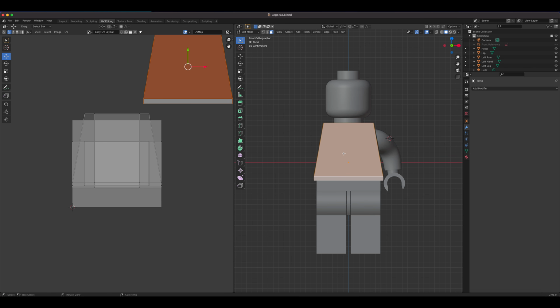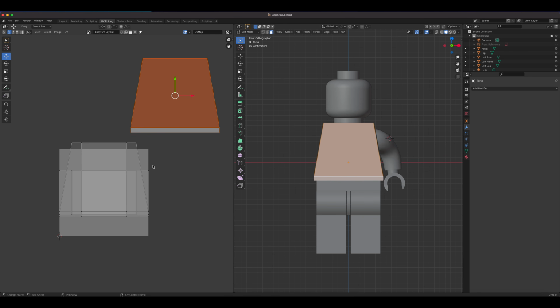See, when you are not selecting everything here, you can't see all the other selection. That's because this particular tool is not on by default. It's the UV Sync Selection. It looks like a slanted up and slanted down arrow. If you click this on, it shows you everything that's part of the body without the selection. So as you can see here, if I just select the front, you still see those. Let me show you when it's not on.